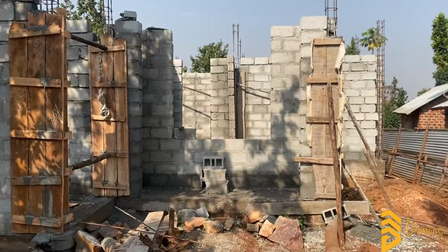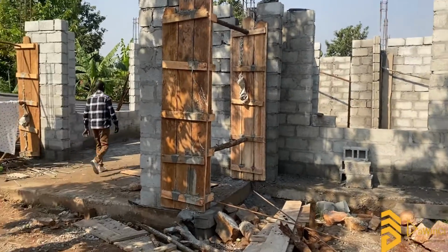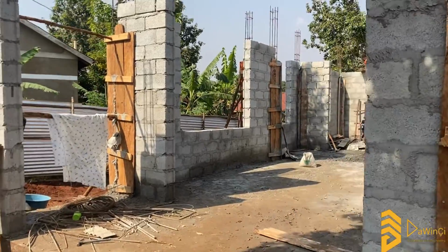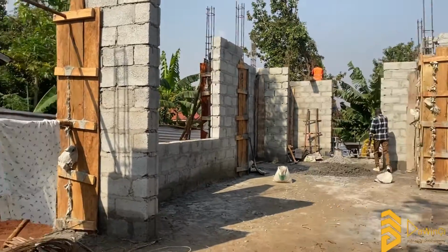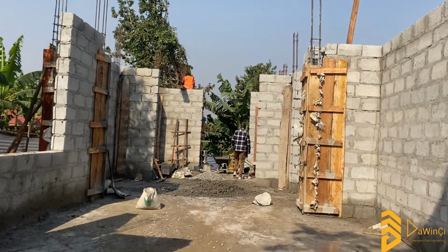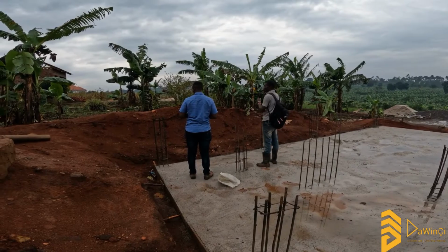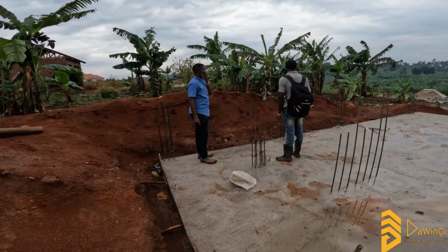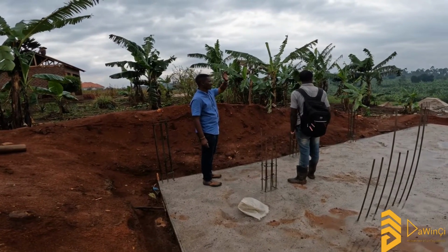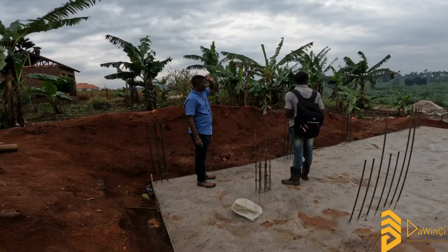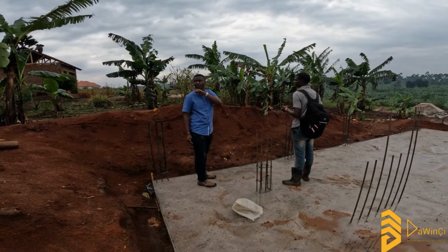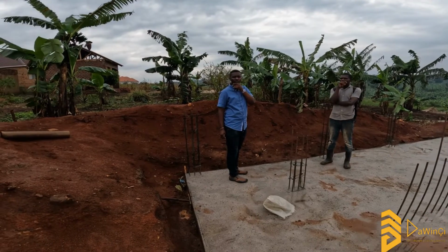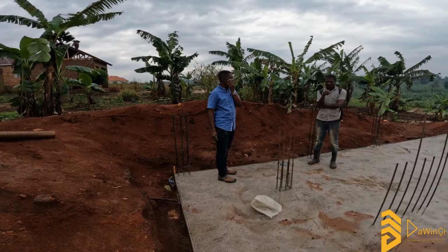Okay, anyway, and also the other way that this can be achieved, most of you see that for the projects that we've been doing here and there, we usually cast the slab before we even do the walling. Of course, some people usually do the brickwork and finish the whole superstructure, finish the whole shell, and then they come and cast the slab later. The reason why we cast the slab at an early stage is so that we can literally cover all the walls, so that the slab carrying the loads of people and beds and tiles and all that, all the loads are actually uniformly distributed onto the plinth wall, so they help the structure act in unison.